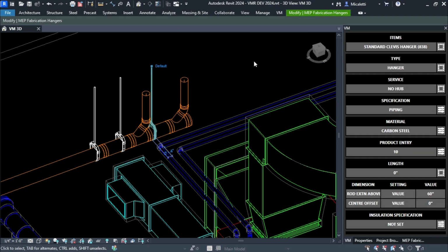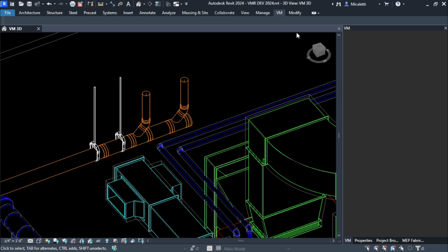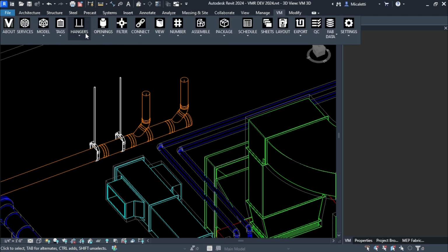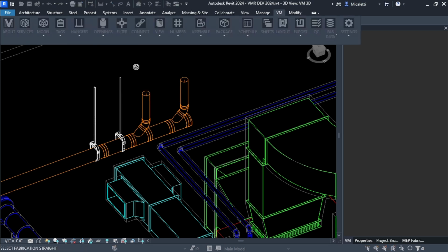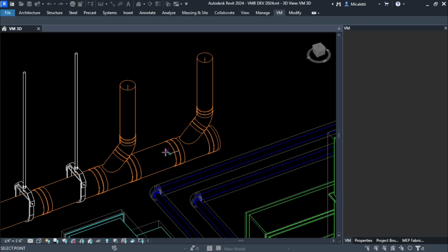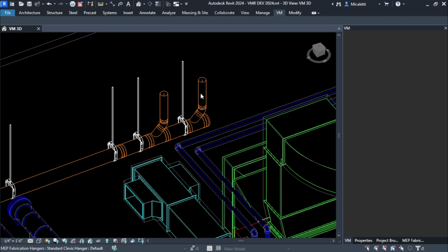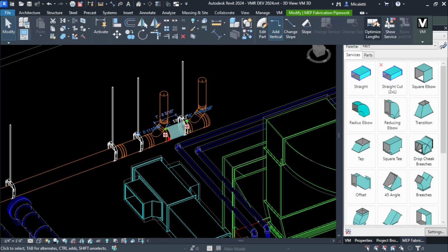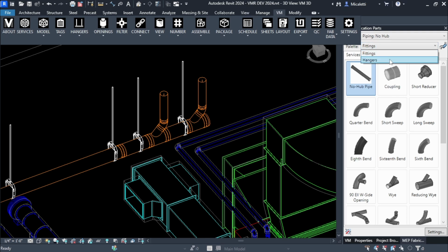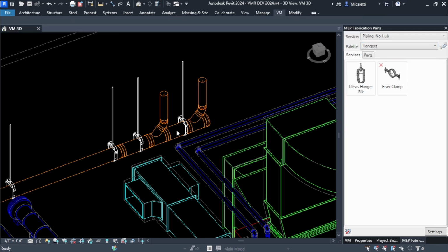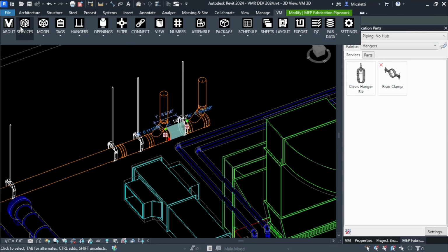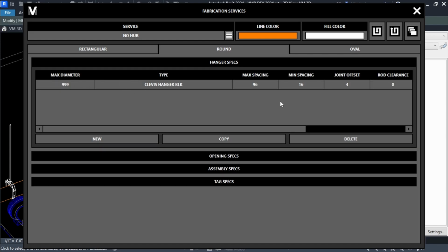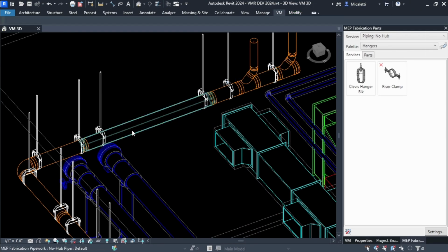But say it didn't give you one here, we do offer manual hangers. So we can come up here and we can say, put a manual hanger on this straight right here. Now in this way, I didn't have to go pick the hanger, right? Show service. Go to hangers, and then I have all these hangers to select from, and I'm not sure at this size pipe with this size insulation, what hanger am I using? We're not leaving that up to the designer. That's all built right. You're still getting the hanger in the service that was spec'd, right? But you can place them manually now wherever it's missing one.